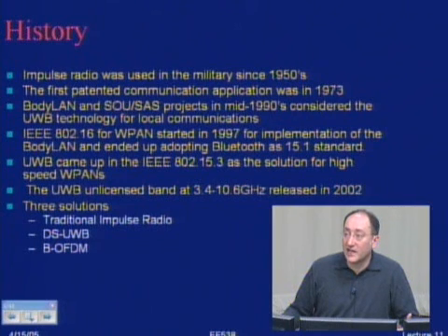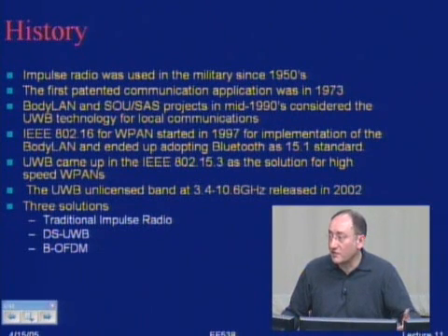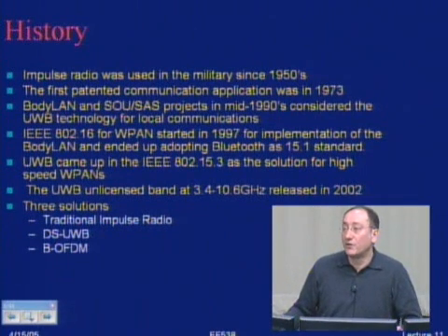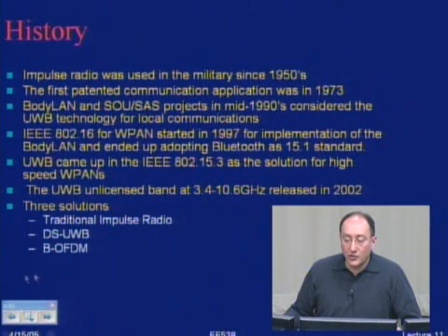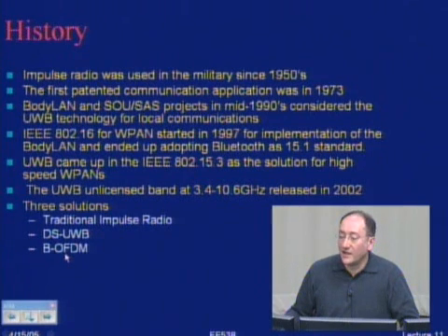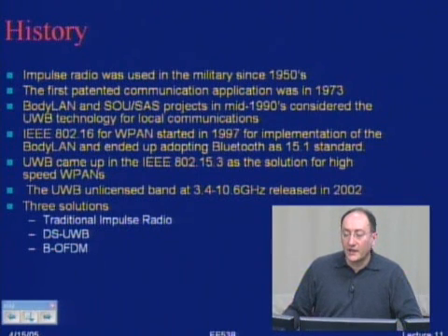So finally, wireless LANs, starting from direct sequence spread and frequency hopping, they go to CCK, but they land into OFDM for broadband. So we have two camps, really. A camp with a little tendency towards cellular, and a camp with a little bit of tendency toward wireless LANs. And those two proposals come to 802.15.3. And then the band that we have available is 3.4 to 10.6 gigahertz, which finally got released in 2002.